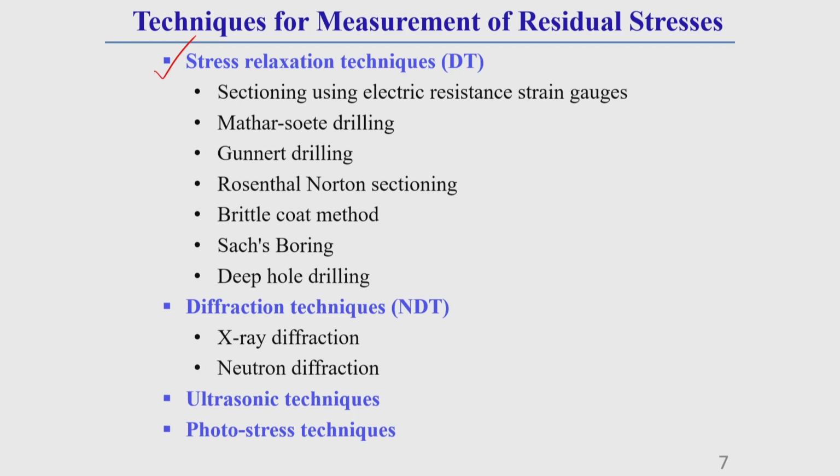Whatever names I provided earlier are more or less similar to these, but depending upon the inventor's name, these techniques also have some different names. Like the techniques which I will discuss here: the sectioning technique using electric resistance strain gauge. I will discuss the Mathar-Soete drilling technique. I will discuss the Gunnert drilling technique.